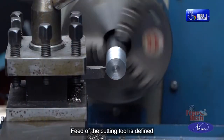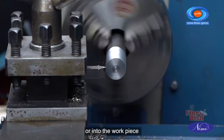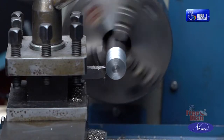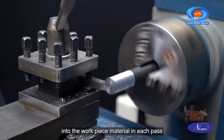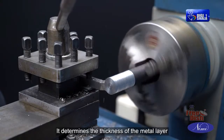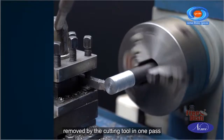Feed of the cutting tool is defined as the distance it travels along or into the workpiece for each pass in unit time. Depth of cut is the penetration of the cutting edge of the tool into the workpiece material in each pass. It determines the thickness of the metal layer removed by the cutting tool in one pass.